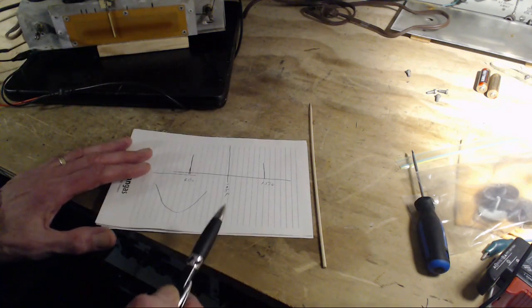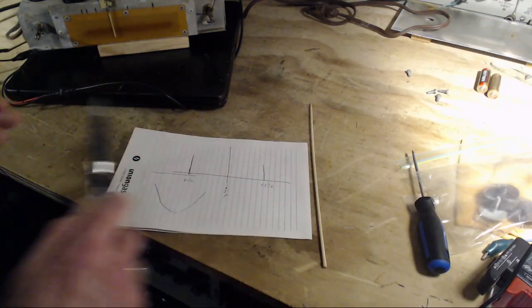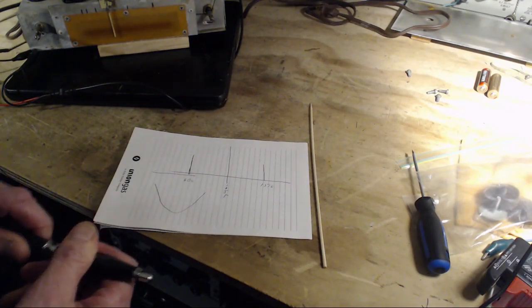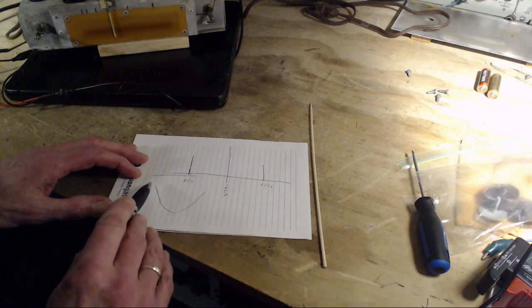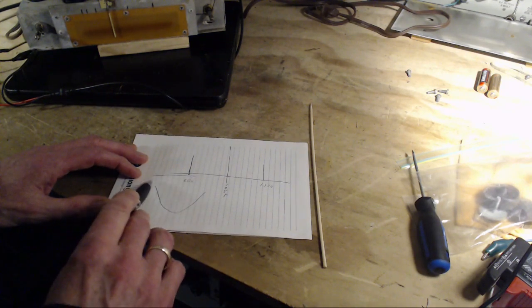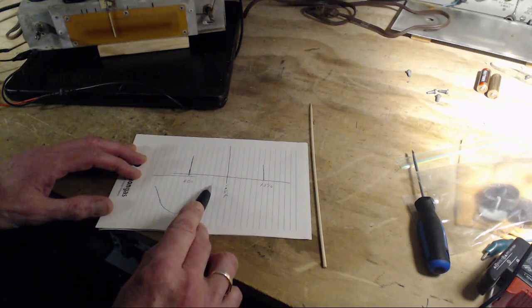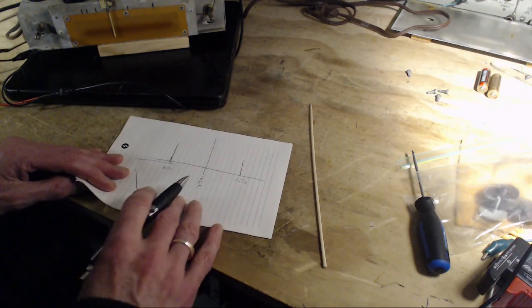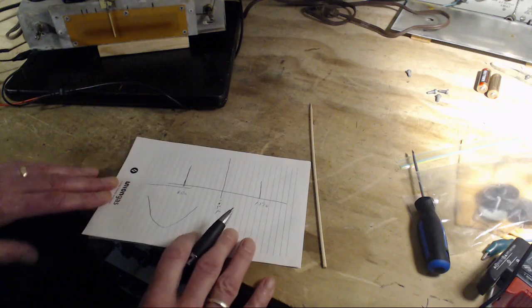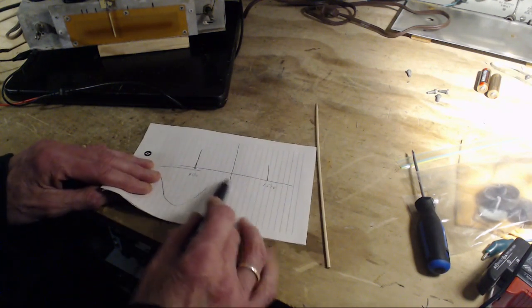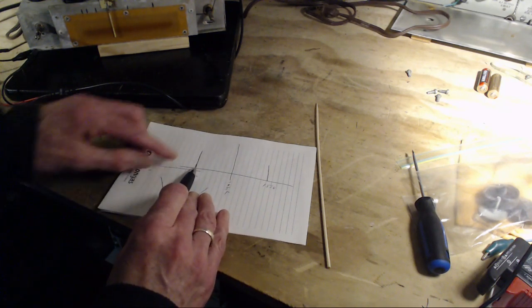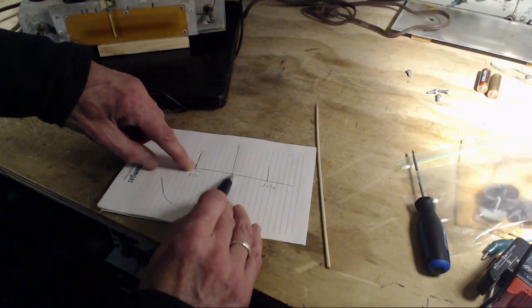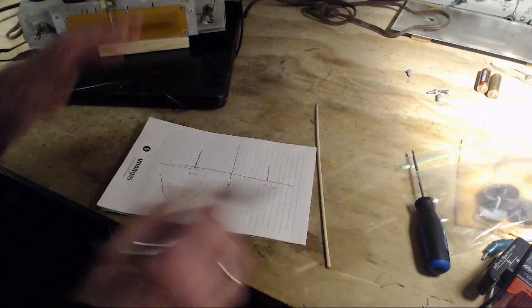Now I've heard this in lots of radios, and I've always wondered what the heck that is. And what I resolved in my head anyway is you're definitely hearing an influence from an image signal. This characteristic sound, this pitch going down and back up, can be figured out. And we'll do this very, very quickly here. So let's say everything is tuned exactly right. So the image is appearing right on top of the signal you're interested in. And this is exactly 455, and that's 455, and the IF is tuned to 455, and everything is as normal as it ever could be.